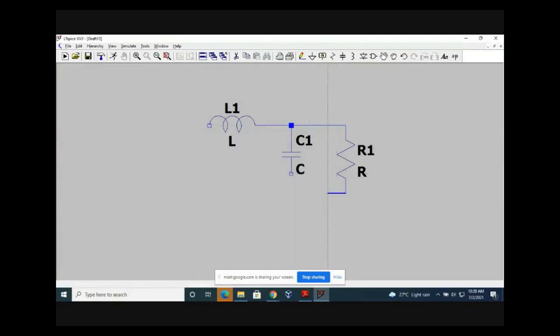And so how did you rotate it? Control plus R, and then click on the component? If you are asking about the wire... No, sir, for the component L1. Okay, so see, I just clicked on the inductor, and now the inductor is there. I want to do a rotation, so I'll just press Control plus R. It is rotating, and I want the other form, so I press Control plus R three times, and then I keep it there by left click.